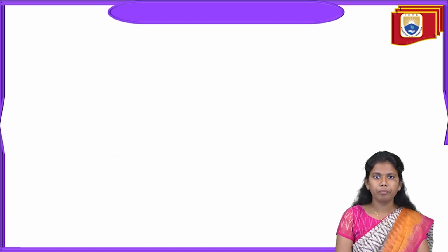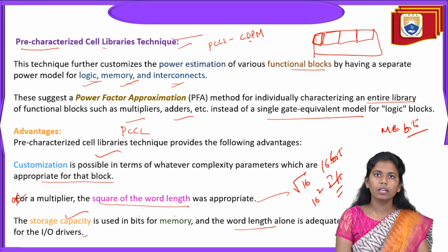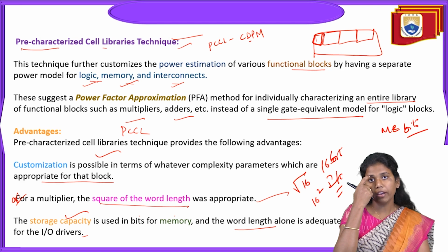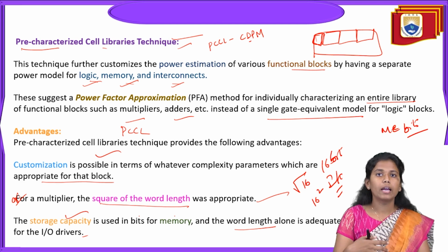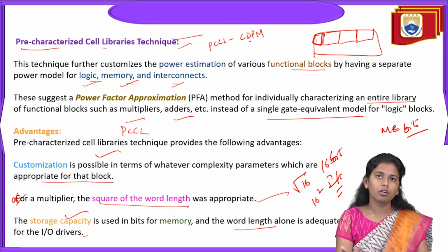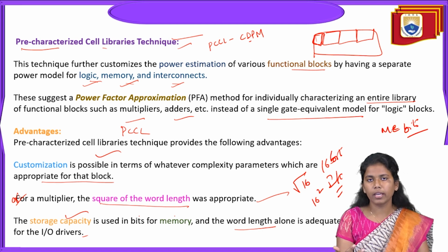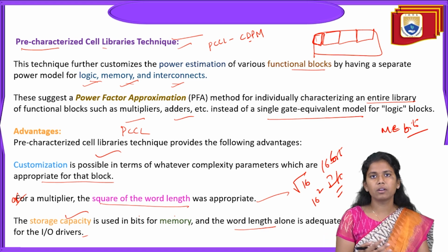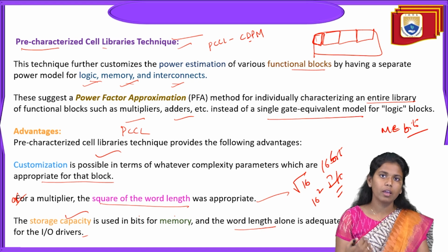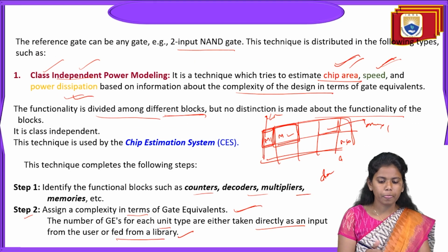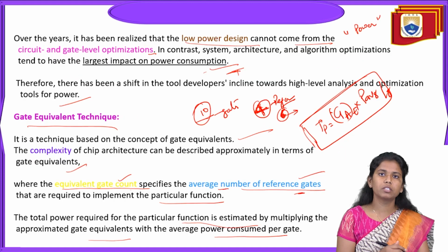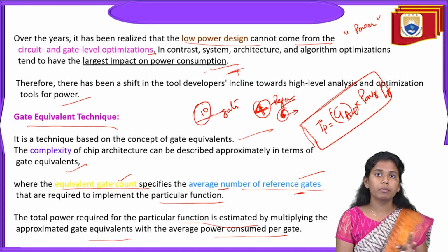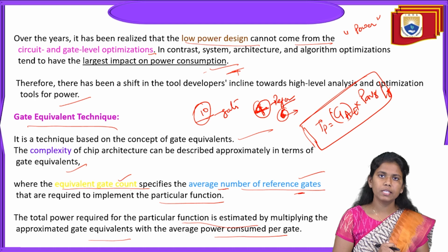So this is all about today's topic, that is the register transfer level. In the register transfer level, we have discussed what it is, how it helps designers, and what sort of tools help us design the layout. There is an interconnection between the logic synthesis tool, the placement and routing tool, and the physical layout. And then we came across the power estimation techniques.